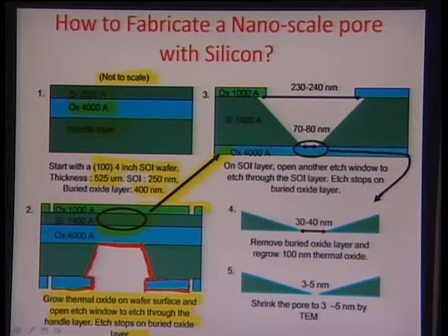So essentially this is that oxide 1000 angstroms layer which you had grown earlier on the top of this silicon layer, which is 1400 angstroms essentially, and here this is thermal oxide. So you can say that earlier the silicon was 2500 angstroms, but because oxidation is a diffusion driven process, the oxide layer formed is about 1000 angstroms, making the pure silicon about 1400 angstroms or so.